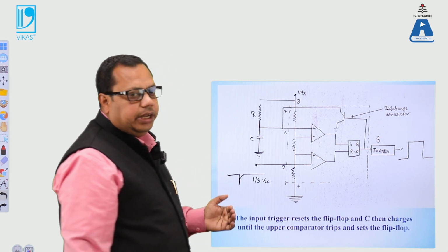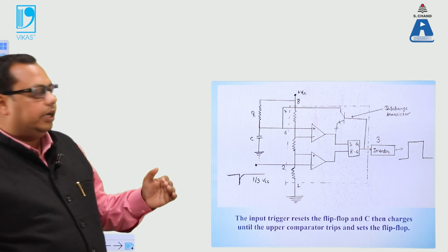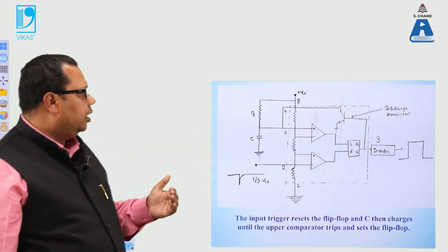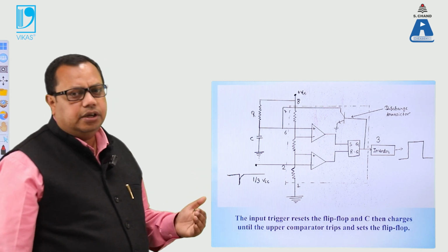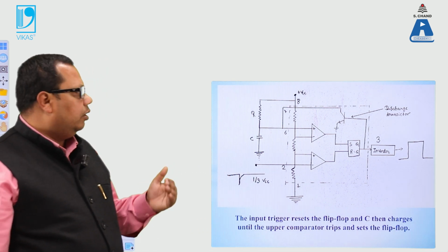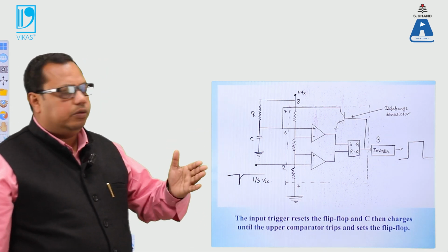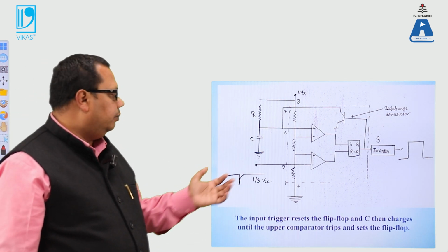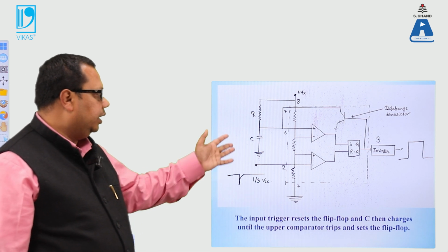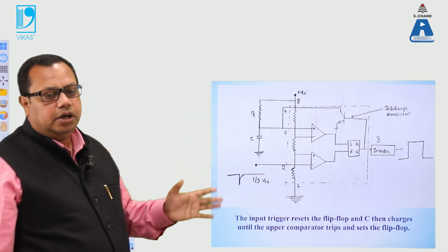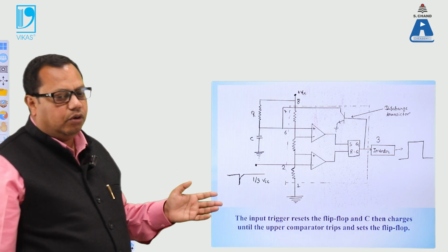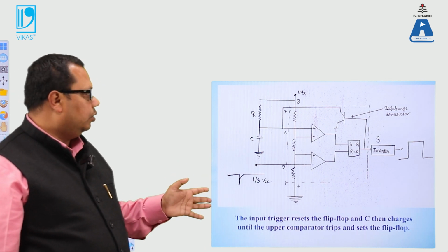So here we are studying how the RC circuit, the circuit that we have learned in the previous modules, is connected with the operational amplifier, and the op-amp output we are connecting with the discharge transistor, and the multivibrator circuit is ready, which will work from the lower potential to the higher potential, and which will work for different triggering voltages also.